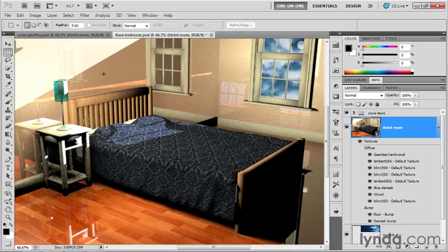The big problems with what we're seeing are the big swath of light in the upper left-hand corner. That's because our scene, as you may recall from the previous chapter, has no ceiling. The ceiling is set to 0% opacity. And furthermore, see this little band of light right there? Well, that's some light that's being cast all the way over on the far right-hand side of the scene. We can't see it. It's way over this way. However, it's being reflected in that wall, and that's a problem. And so we're going to have to add a ceiling to the scene and eventually a far wall as well in order to cut that light. And we'll be creating that ceiling and adjusting our moonlight in the next exercise.